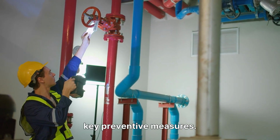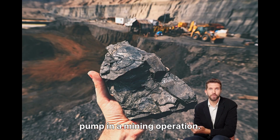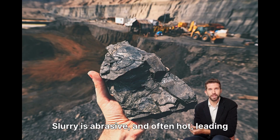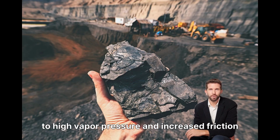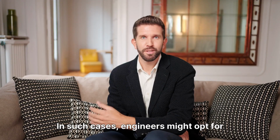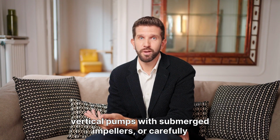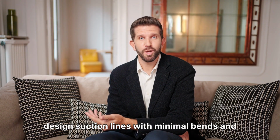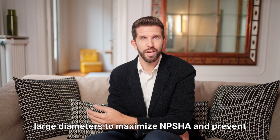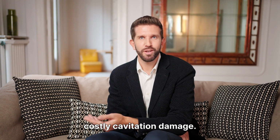are key preventive measures. Let's consider a real-life scenario: a slurry pump in a mining operation. Slurry is abrasive and often hot, leading to high vapor pressure and increased friction losses. Maintaining adequate NPSHA is extremely challenging but vital. In such cases, engineers might opt for vertical pumps with submerged impellers or carefully designed suction lines with minimal bends and large diameters to maximize NPSHA and prevent costly cavitation damage.